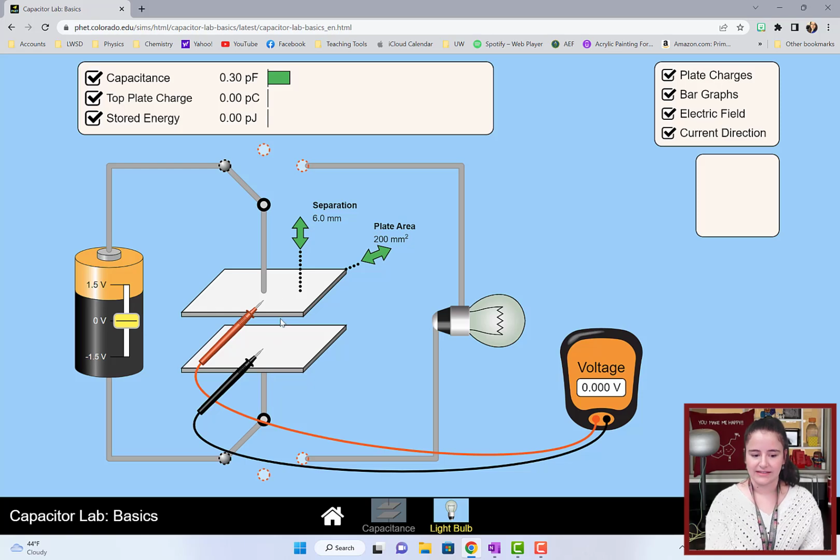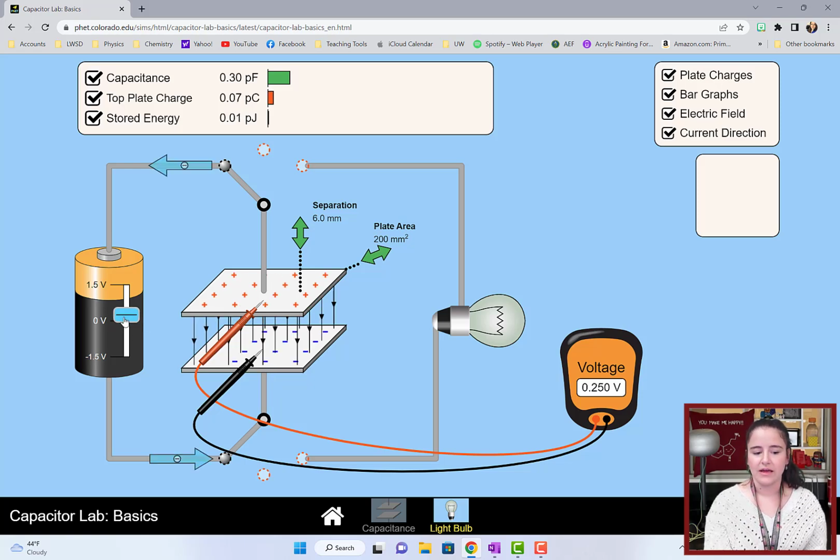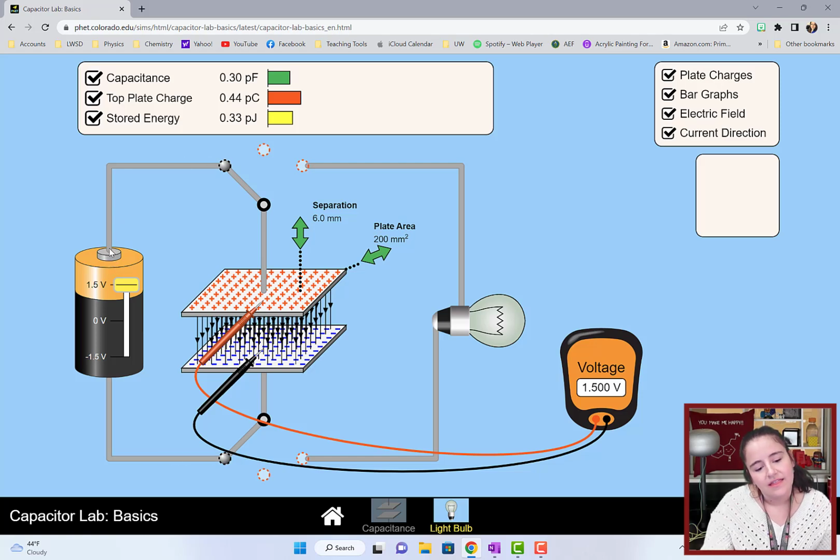Okay, if we can kind of visualize this, we have two charged plates. So if I apply a potential difference to them, that is going to push the positive charge onto this plate, which will repel the electrons in this plate, which will attract the electrons in this plate and allow that positive charge, or that current, to keep flowing through the capacitor until it looks like this and is what we consider fully charged. We can see here that the voltage across the capacitor matches the voltage of the battery. Okay. Now, the energy of a capacitor is stored in this electric field.